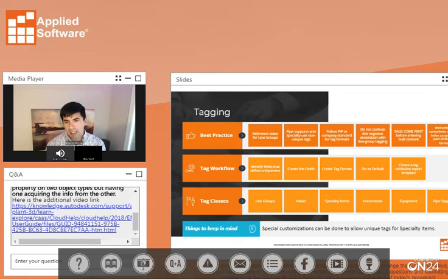Adding an index, which is not visible, means you wouldn't show the index as part of the instrument bubble, but it's still going to have the same type and loop number on it. In some cases, it's appropriate to add an index property for your instrument tagging just to make sure that they're all physically unique, even if on the drawing they don't appear to be completely unique. Great.